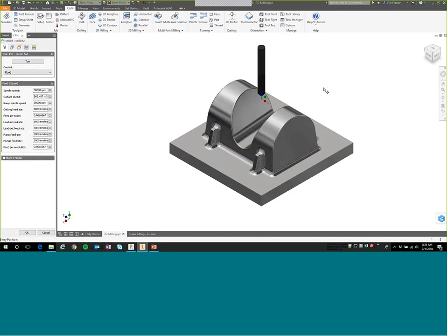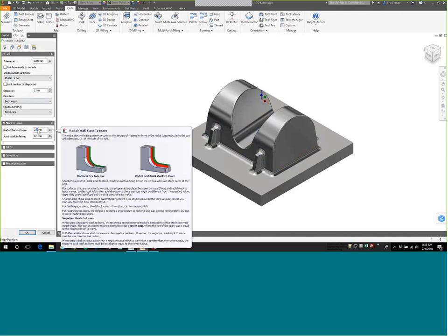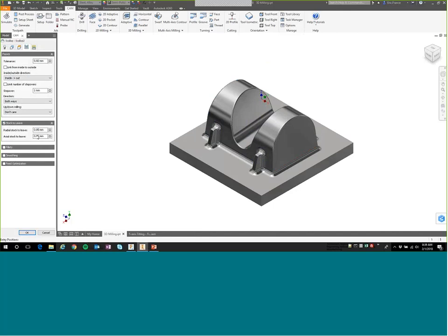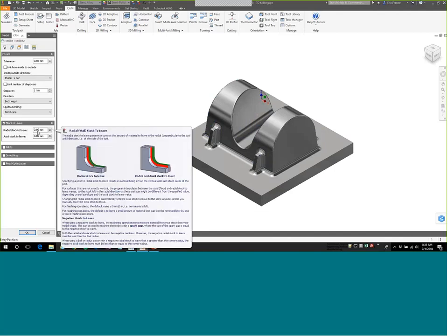Right, so we've identified that smaller ball, and the geometry it's going to pick up automatically, so we want to make a couple adjustments to some of the pass settings that we have in here. We want to go from the inside out. We do want to control our step over and have stock to leave. And we'll go ahead and drop that down some, 0.05 millimeter, sorry, 50 thousandths of a millimeter.